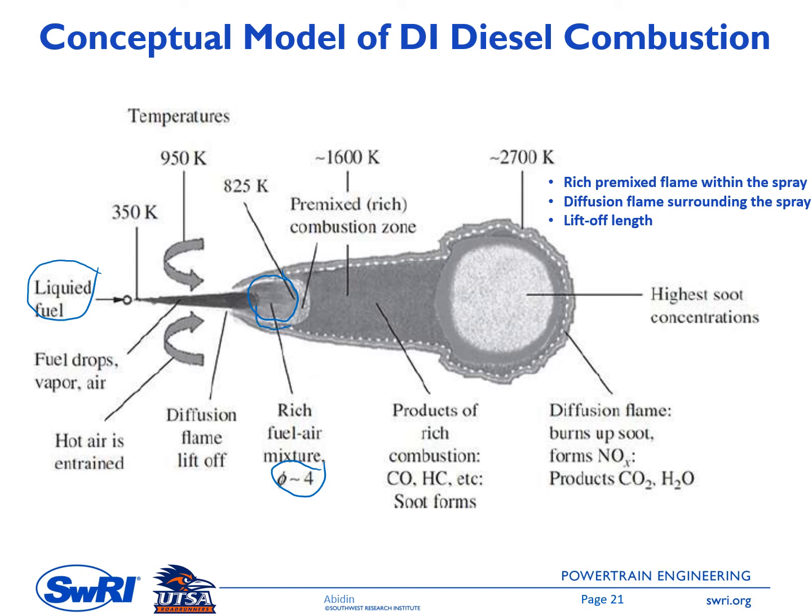This is just part of the combustion product, and the combustion was incomplete, so it still contains some reactive species, or sometimes called radical species, and then it will increase the temperature of the mixture further from 825 to 1150, and then later to about 1600 Kelvin.